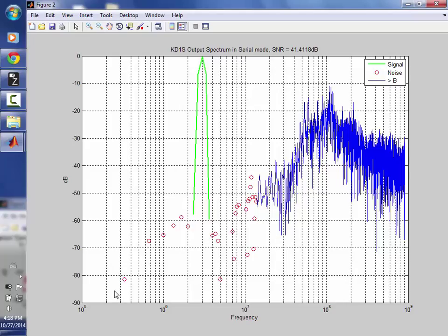So just as a sanity check, why is the spectrum going up like this? Noise shaping. And then what if I increase the oversampling ratio? If I increase the number of points I oversample, what happens to this change from red to blue if I increase the number of points I'm averaging? Yeah, and we can rerun the sim and show that. It pushes it down, so we have a smaller bandwidth. And then a peak here, you can see how it's peaking at whatever the sampling frequency is, and this is out of band noise, which I don't use in my SNR calculation.